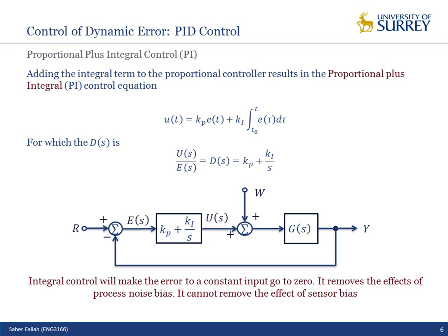If the steady state error is not important for us, there is no reason to use it. Just a proportional controller or PD controller is enough. If the steady state error is important for you, at least you need a PI controller, if the steady state error is not 0 with just a proportional controller.